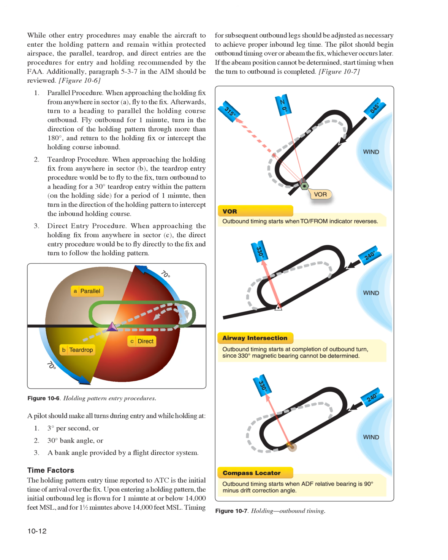3. Direct entry procedure. When approaching the holding fix from anywhere in sector C, the direct entry procedure would be to fly directly to the fix and turn to follow the holding pattern. Figure 10.6. Holding pattern entry procedures.